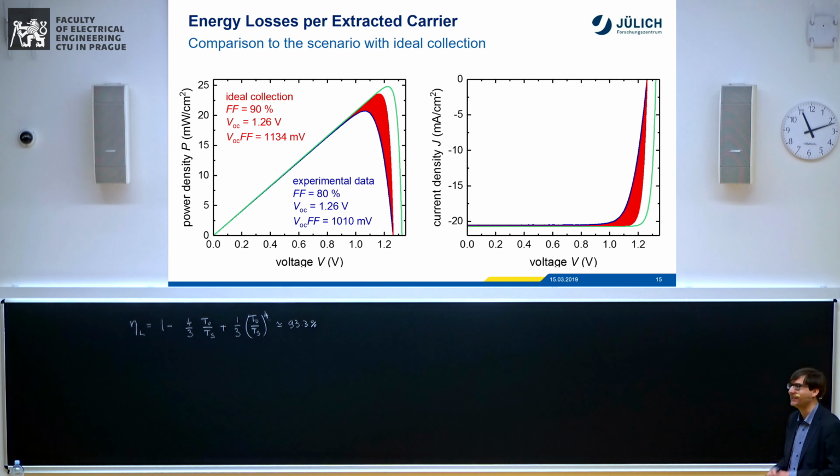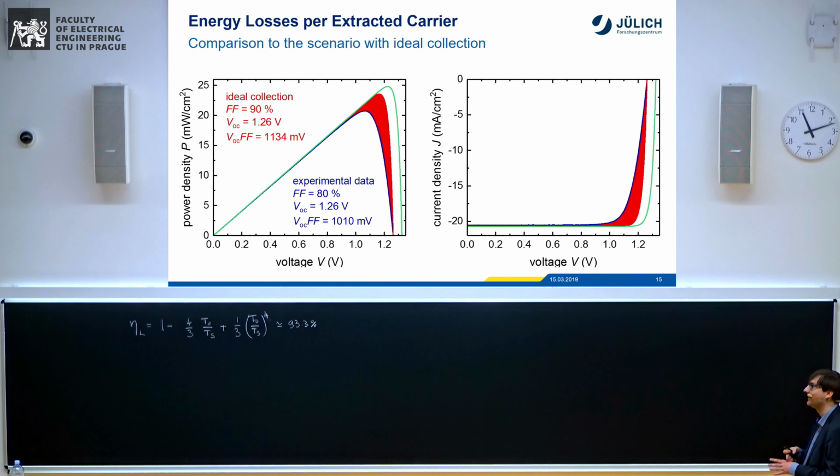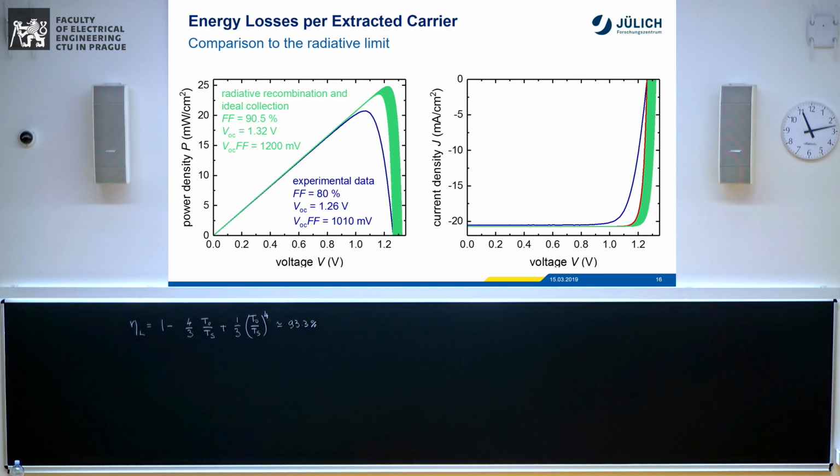Although everybody will say 80% fill factor sounds quite all right. Yeah? It's still quite far away from the theoretical limit, much further than crystalline silicon, where you can get to 81, 82% experimentally, and the theoretical limit is 84. Yeah? So there's much less to gain there than here. And we have series resistances that are actually quite horrible for crystalline silicon standards.